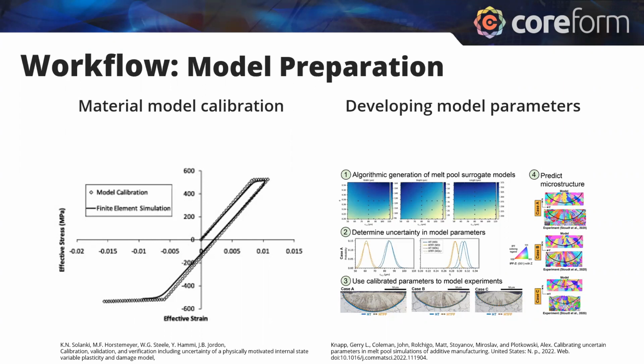So there's a Mullins effect that occurs. You'll typically have some test data, and then you'll want to fit this test data to different material models to run some analysis. So you're calibrating your material model. And that's even before you're able to look at your engineering scale problem.